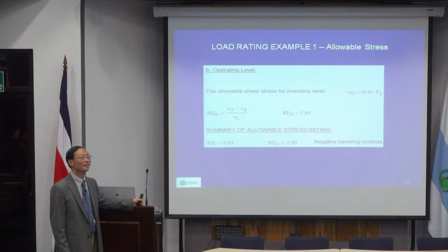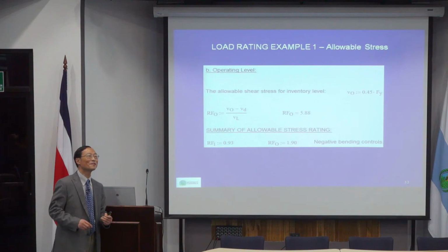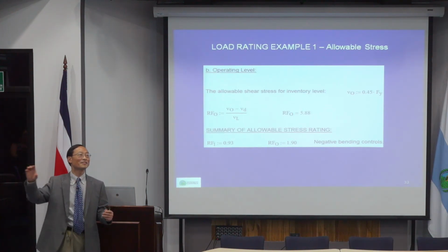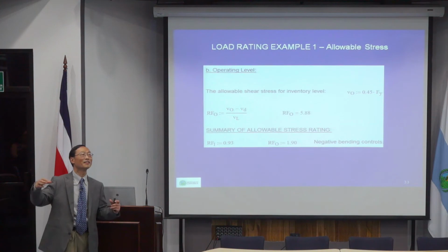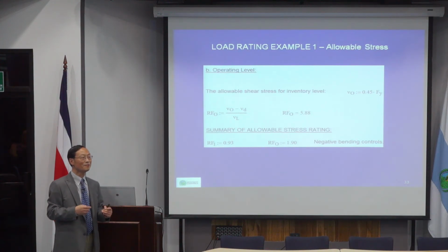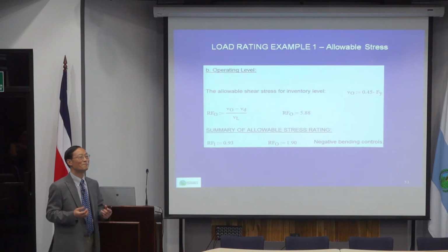Especially if you use different methods, like most bridges were designed using allowable stress, and allowable stress design is pretty safe. You spend a lot more materials than otherwise, so the overall safety of each component is larger than with the LFD method. But because of the unevenness, some elements might have smaller safety factors, though I haven't found that. I've read a lot of bridges designed for allowable stress, and they always have big rating factors for the LFD method. But nobody knows. It can be a certain chain that was built very small, and it may just show up somehow.